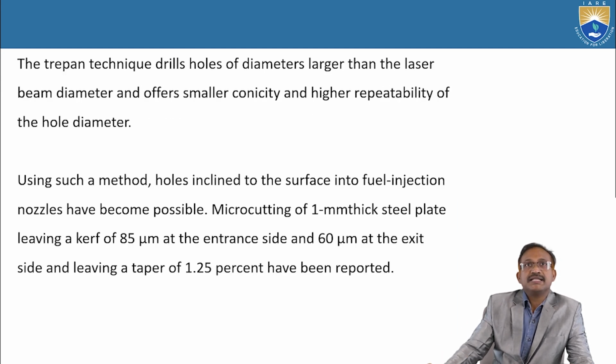The trepan technique drills holes of diameters larger than the laser beam diameter and offers smaller conicity and higher repeatability of the hole diameter. Using such a method, holes inclined to the surface into fuel injection nozzles have become possible.